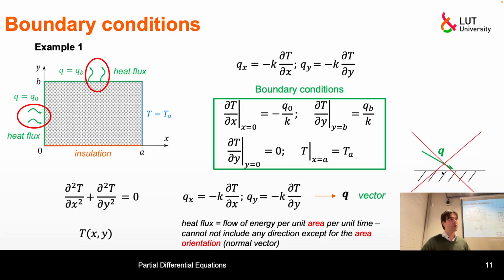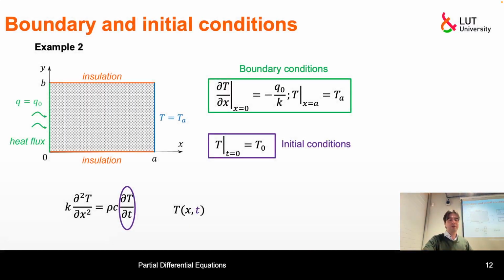So we have one direction of the plane, but what comes to this plane is not a vector, it's energy. So then it's a scalar quantity. Okay, so please be careful about this vector. Don't be confused that the software that you're using doesn't allow you to define the direction of this vector when you're applying a boundary condition, because this part is already defined by the orientation of the line or whatever surface you're applying it to. Okay, so going back to other examples, this must be faster.